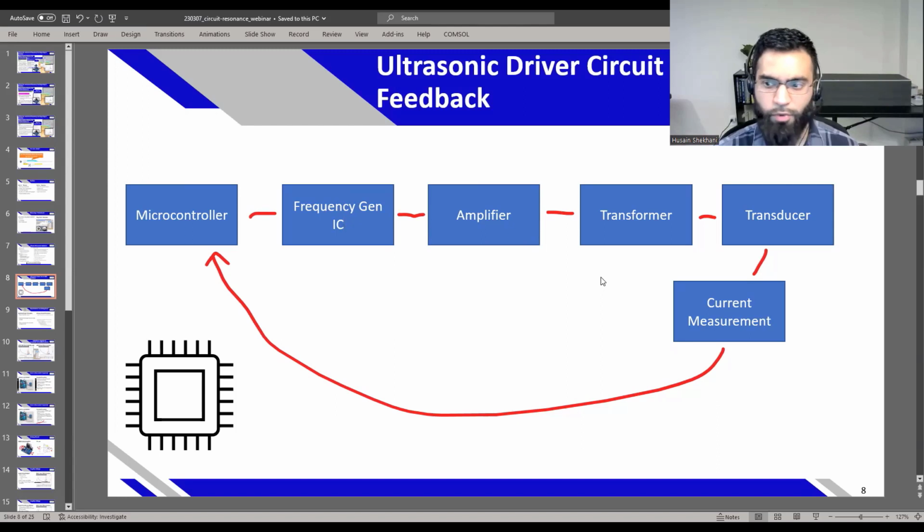We'll see about our product that we're describing here today, the atomizer, but we'll keep going. We need a transformer because the amplifier is likely not made for your transducer, so it won't be well matched to deliver maximum power. In many cases the amplifier is overrated for your transducer, but that's okay, especially if you're plugged into the wall, for a medical, surgical or welding device. But at very high power levels you do need to match the power, and you can't build an amplifier to that spec.